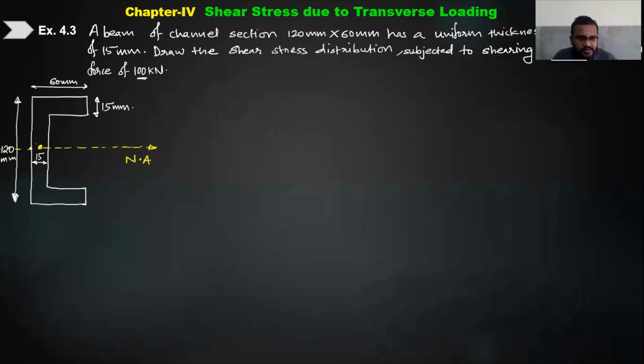So let us take this as my section 1-1. Then I will be finding out at this particular section, that is section 2-2. Then I will take the bigger layer up to end of this, that is my section 3-3. And then the top layer is already 0, we already know. Bottom layer is also 0. The lower layers are symmetric. This section is symmetric, so no need to solve for the entire section. We can solve only half of the section, and the rest part is done.